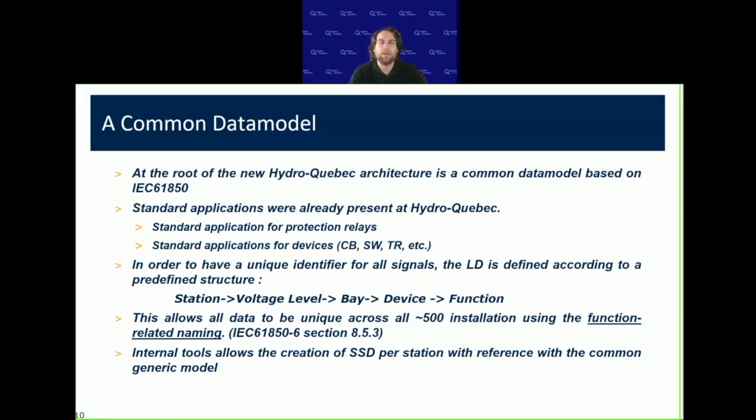Then, from different internal tools that we developed, we're able, for now, to give an SSD, the specification file based on the 61850 standard, for each of the individual stations that we're migrating to 61850. In the future, we hope to provide an SCD as all the different information becomes known. It's a matter of developing the tools in order to provide a valid and validated SCD for each of the stations.